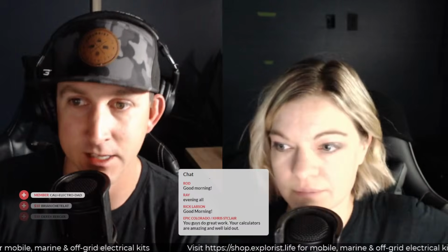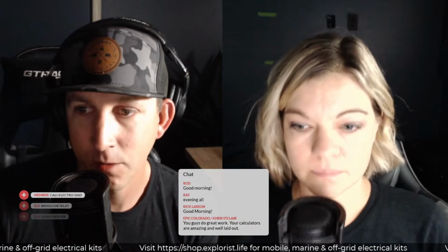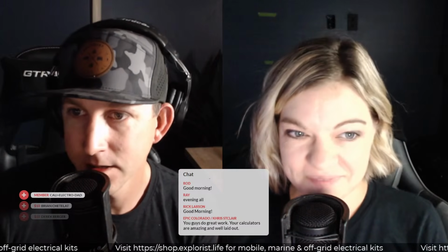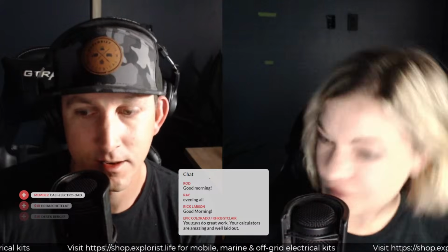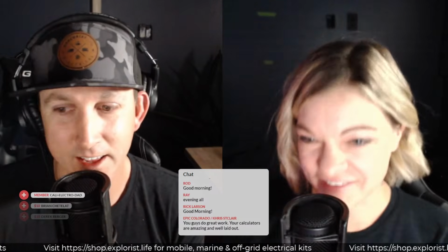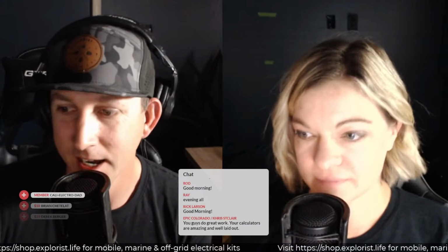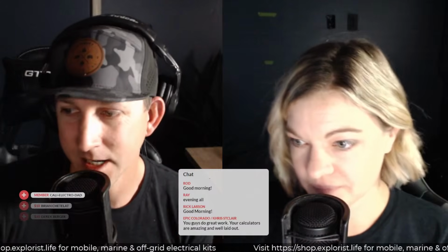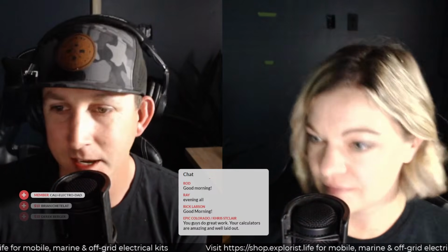So it was only seeing the coffee maker basically, because I think if we turn that off and go into that next page, yeah, it says AC inverting capacity needed 0 watts. That's not right. You have to have at least one, which I have as the default on there. But realistically, we need to go in there and check, next to simultaneous AC loads, what devices we want to be able to run at the same time.